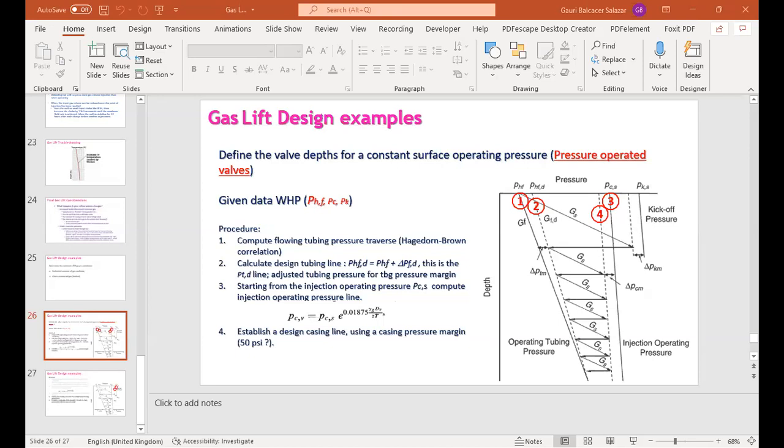And so with this, we have production rate, the inflow pressure, and the outflow pressure. And so we are able to build this plot of inflow and outflow. The inflow is given by the production and inflow, and then for the tubing side it is the production and the outflow.